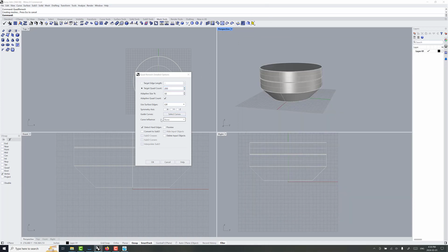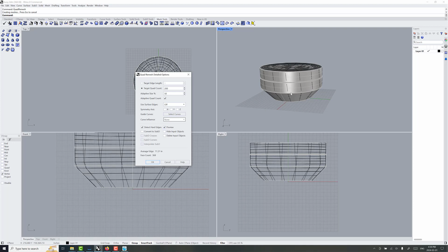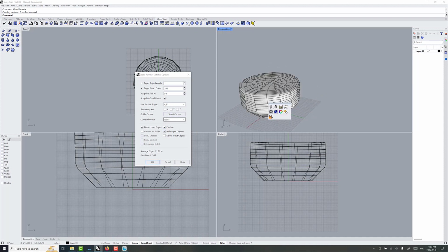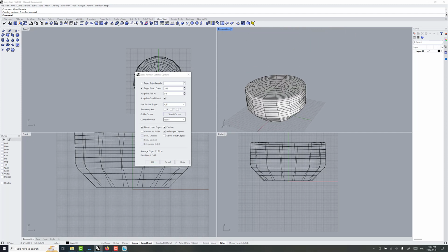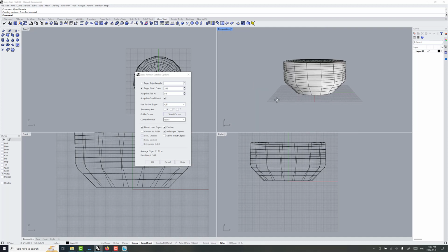This is in Rhino, taking advantage of the quad remesh functionality. This is a step file, a surface geometry that we need to make a mesh from. So just hide the geometry. This is with 200 panels just for this hull alone. And you've got tons of detail in there to handle variations in the wetted area for buoyancy and drag and stuff like that.